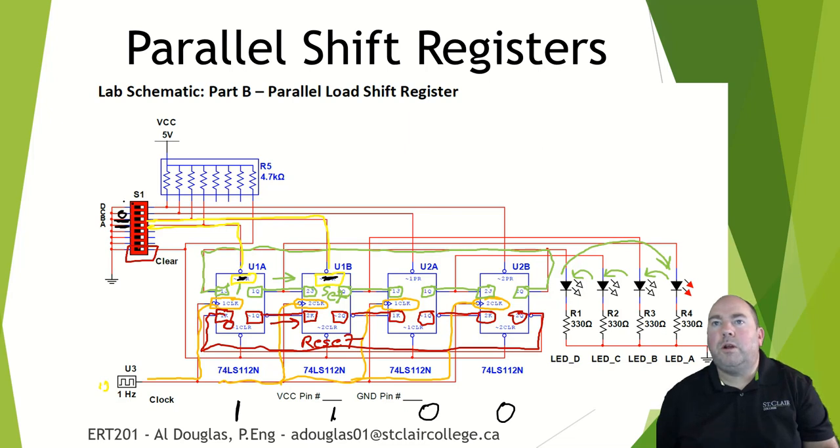And you would make this one off and this one off. So that would put in a 1 and a 1 here, and a 0 and a 0 here. If you set those up as presets and then set them back to the regular states again and then started clocking it, then this pattern would loop around in a circle. Okay?